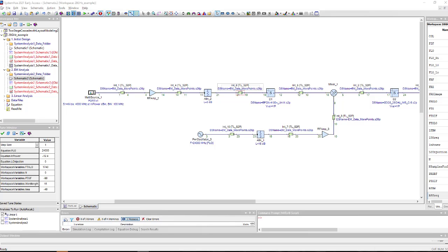We are excited in the latest release of SystemVue 2021 to have a new interconnect parasitic model for you to use to capture insertion loss, mismatch loss, but also coupling effects across your signal chain. This is that upconverter I described earlier, but now in the latest release, we're able to use a more sophisticated interconnect model to capture the coupling between the different stages, but also obviously their insertion loss and their mismatch losses.